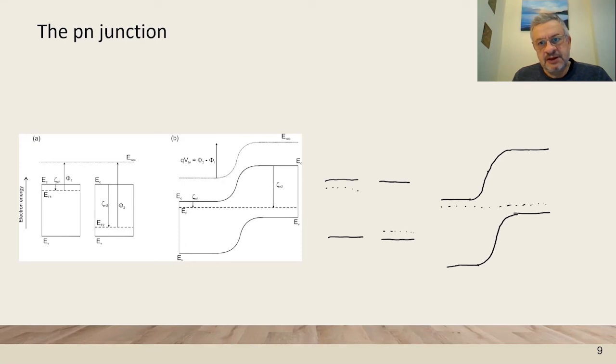And this is different from the contact potential difference because this region is quite extended. It will depend on the doping. When there is less doping, it will be more extended. So this is like two Schottky barriers back to back.